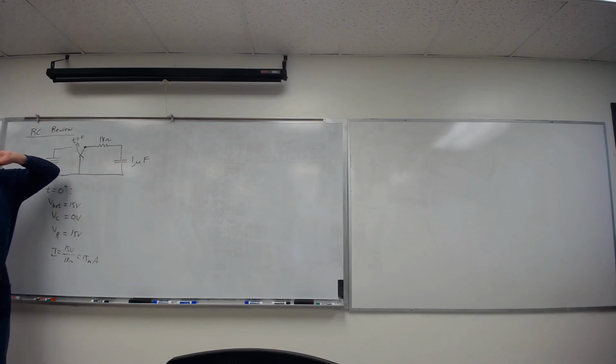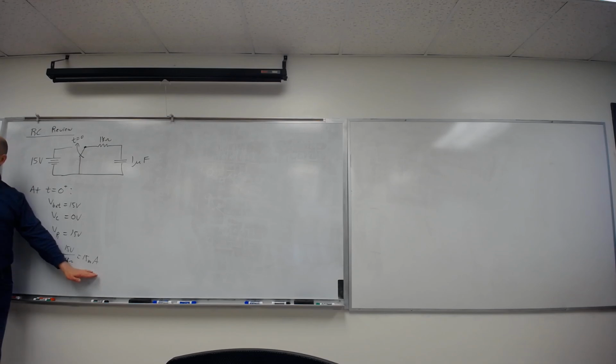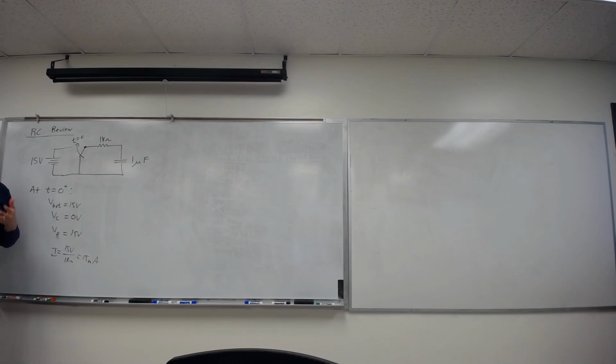We will talk about current at times flowing through the capacitor, but of course no current's flowing from one plate to the other. What's happening is we're stripping charges off, moving them through here at 15 milliamps. 15 millicoulombs per second are being moved from that side to this side. And as it moves, the charge builds here. We have a voltage proportional to the charge. When this voltage ends up at 15 volts, then I'll have 0.